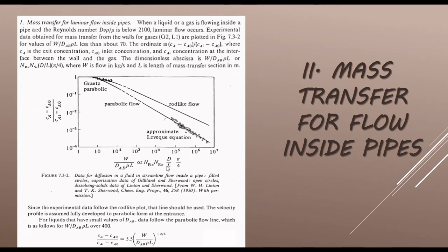The rest we have defined already in terms of the two dimensionless numbers that appear. So if you don't have the information for this, you can utilize this particular expression for the abscissa. That way, once you have chosen the appropriate curve to use in here, we only have two: one for rod-like flow and the other for parabolic flow.